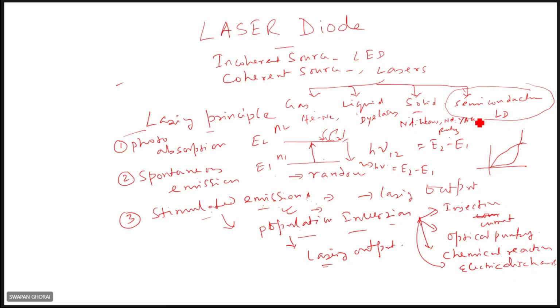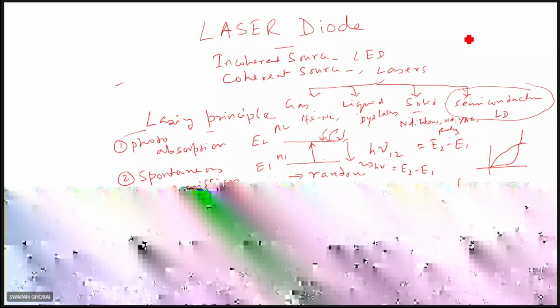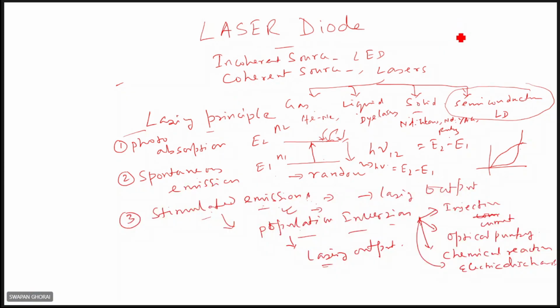And the question is why so many types of lasers? Why do you consider these semiconductor lasers? The answer is very simple. If you use these other lasers, you need an external modulator to modulate their optical output. Ultimately, within the fiber, light is not simple continuous light. It's a modulated optical beam that is propagating, modulated by the modulating signals.